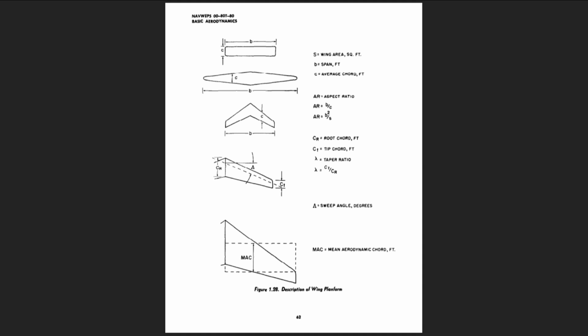The aspect ratio is a fineness ratio of the wing, and this quantity is very powerful in determining the aerodynamic characteristics and structural weight. Typical aspect ratios vary from 35 for a high-performance sailplane to 3.5 for a jet fighter to 1.28 for a flying saucer.